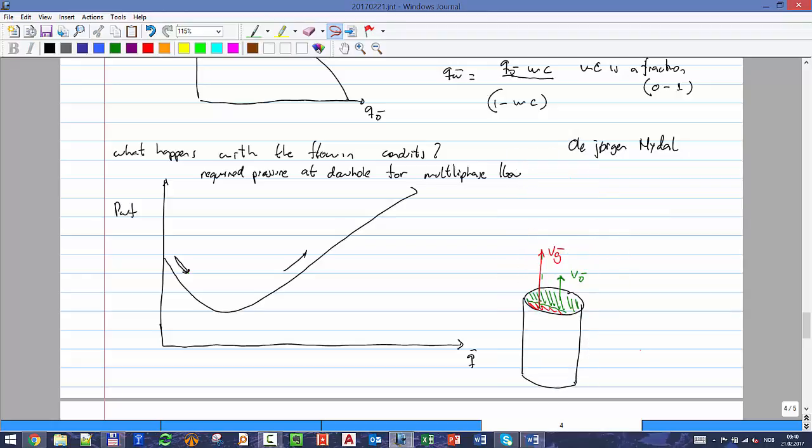So before that, the pressure drop in the tubing depends on two components. Just like single phase flow, it depends on two components: delta P hydrostatic plus delta P friction. When I'm in this part of the curve to the right, the frictional pressure drop is going to dominate. That's a function of rate. And in that part of the curve, that part of the equation is much higher than this part. So that's why it's going up all the time.